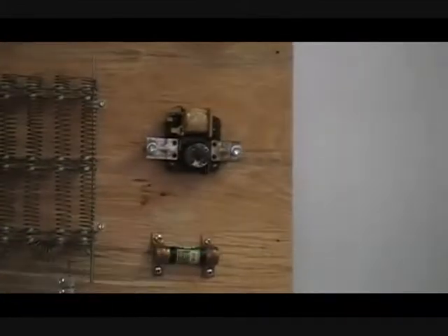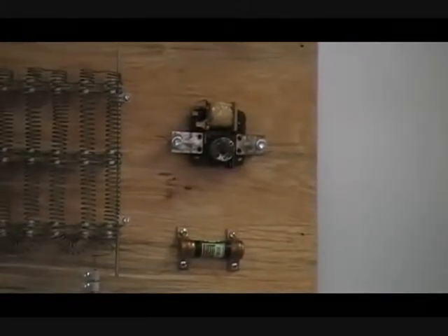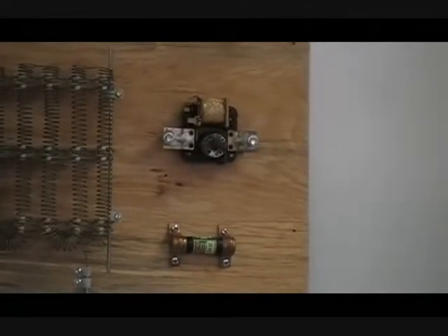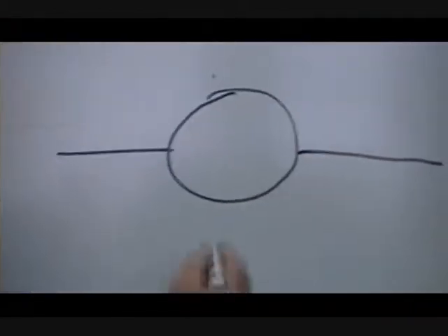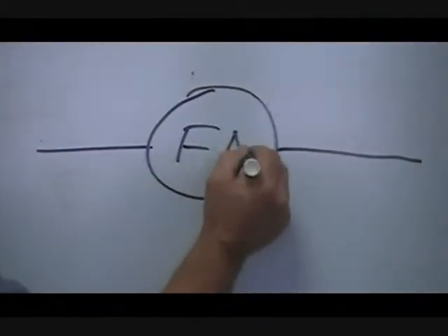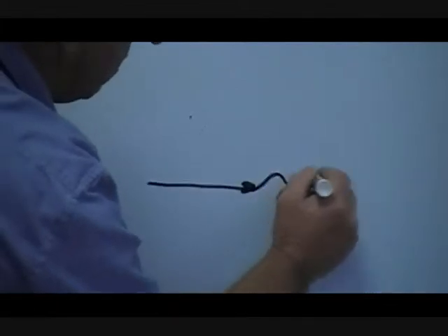I see another component over there, which is a motor. This is a little shaded pole motor. Small units such as refrigerators would have something like that in there operating the fan. Well, how could that be shown? It could be like that. FM, fan motor. It may actually show the windings of the motor.